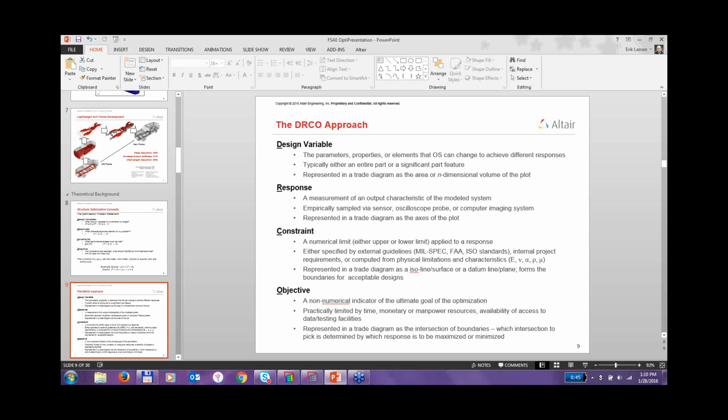So the short answer is there are times where if you do not define enough in the output file, it will complain and it will say, here's the problem. But in all too many cases, you've defined enough for an optimization to happen, but under-constrained or potentially over-constrained the model, and it will come up with a design that's strange or possibly report back that there are no feasible designs. It can't come up with a design based upon the input that you've given it, in which case you typically have to loosen your constraints a little bit. So sometimes it will error out and tell you. Other times you'll know as soon as you take a look at your design and say, whoa, what's going on here?